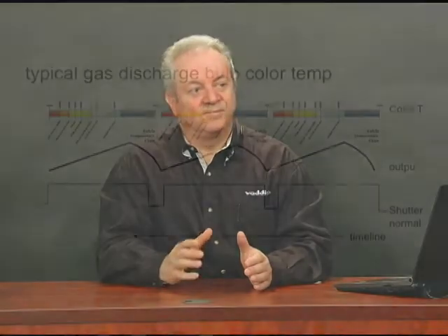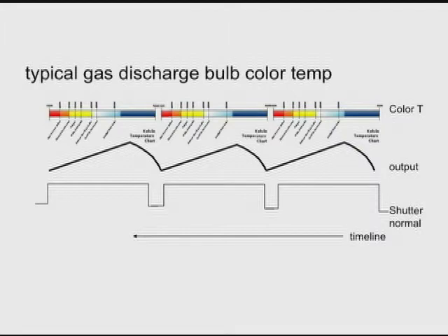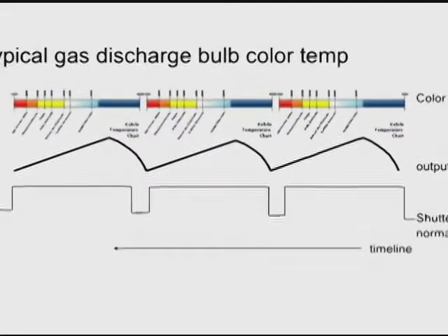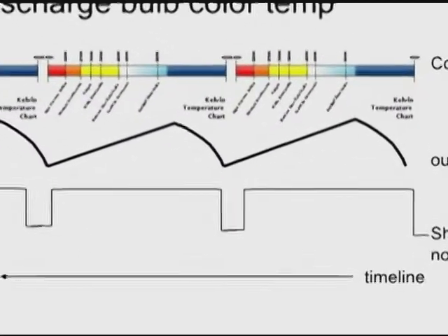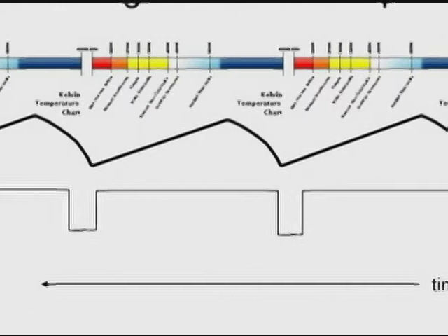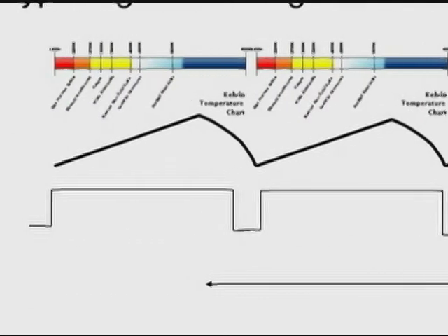It's one still frame. Now the exposure of that frame can be timed either to 1/60th or lower or longer if it's a longer integration. If it's lower in time or longer in time, you will understand now what it causes. In this chart, the gas discharge, when you're using it in fluorescent light, the fluorescent light starts from a very bluish light, goes into red, and then it turns off, and it goes into blue again, and then it turns off. We don't see that, but the camera does.